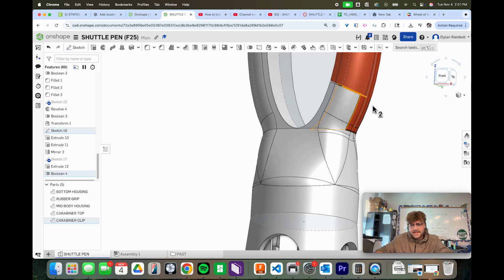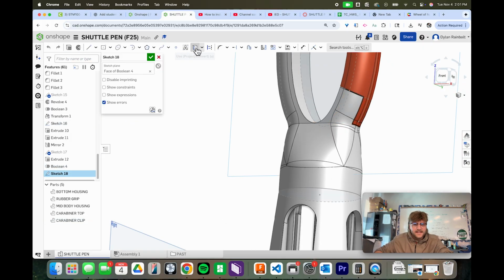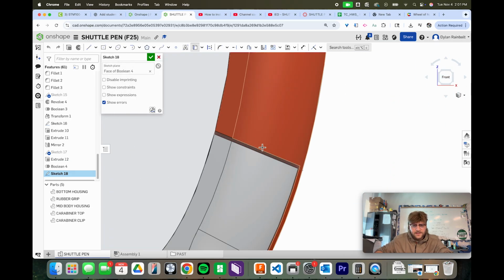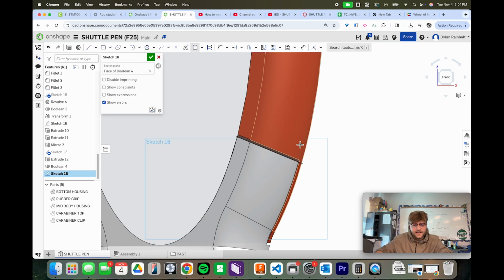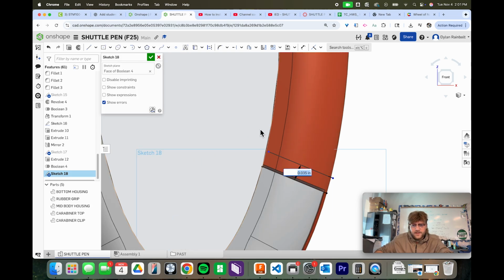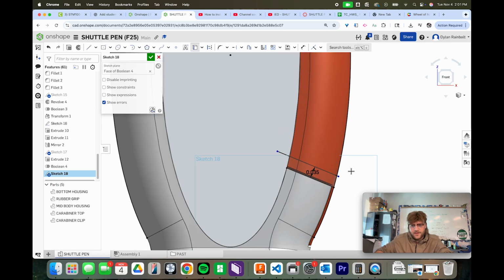that's going to be right on this guy. And so I'm going to create a sketch, and we can use the Use Project to convert if we'd like to, and we can create this guy here. What I'm going to then do is offset that line. So we're going to offset this by a distance of, let's say, 0.035 inches. What I'm also going to do is green check mark that. Then I'm going to use the extend tool. We're going to extend that out. That's already extended out there. We're going to use the Use Project to convert again on both of those sides.